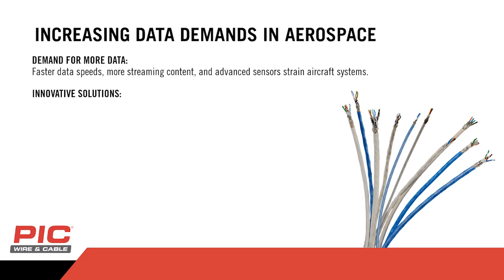A promising development from the automotive industry is the use of single-pair Ethernet cables. The automotive industry, facing similar challenges with harness weight due to the increasing sensor loads, collaborated with IEEE to develop the 802.3 BP protocol. This protocol enables gigabit speeds on a single pair cable rather than a 4-pair configuration, effectively halving the cable's weight and size.